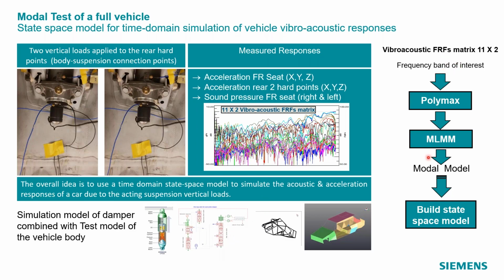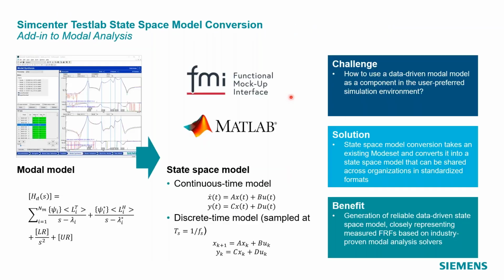So we did Polymax, we did MLMM, and then we generated a state space model so that people could do time domain simulations, even listen to the results of the new damper. By synthesizing the sound pressure levels based on the new damper and the body model, you could really hear what was going on. It will be illustrated also with a demo of these concepts.